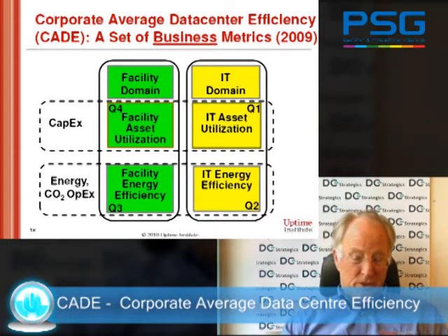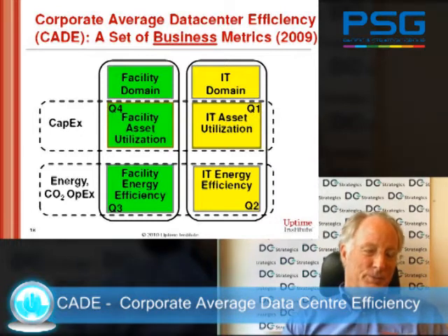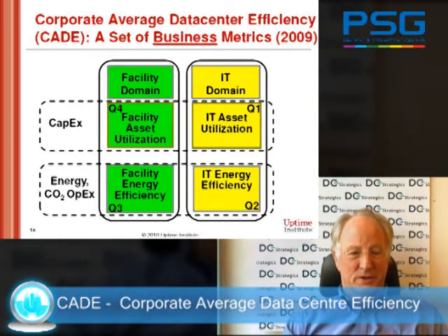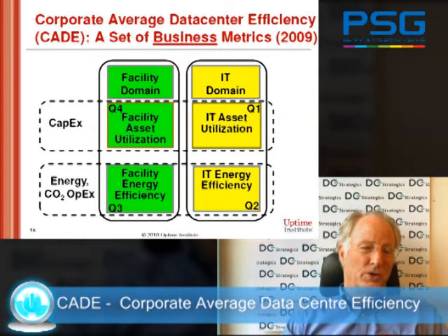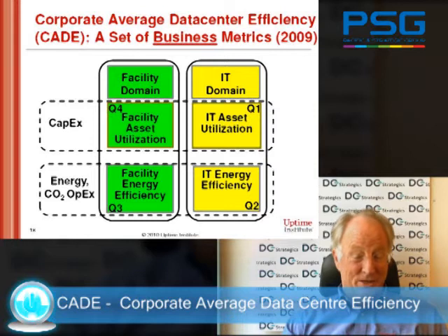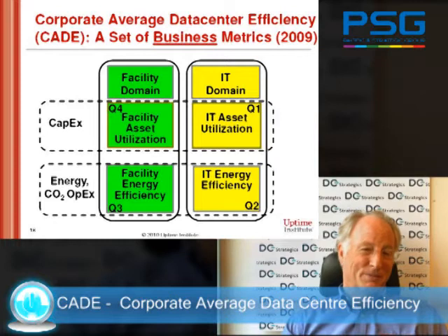And the problem is that the PUE, the largest part of the PUE, the variability, there's 7 things that will cause the PUE to vary. Just looking at a raw number without understanding the 7 factors, the variables that will make it up, you make some bad decisions. The biggest factor on PUE is the percent of load. The people who determine percent of load are the IT people. Now, if the IT people do a good job on Q1 and Q2, actually the facility people will look worse because the load has dropped.